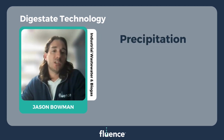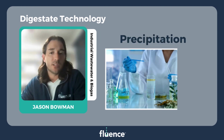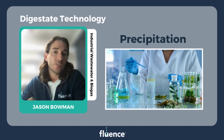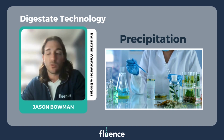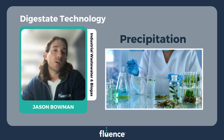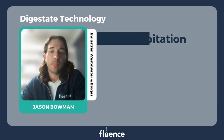Then we have precipitation. So going back to the discussions on ionic activity, sometimes uncontrolled precipitation occurs due to the combination and the concentration of the pollutants in these systems. Other times, we actually need to purposefully create a condition prior to a biological system or prior to a filtration system where we are proactively removing these pollutants before they can cause possible scaling or fouling issues downstream.